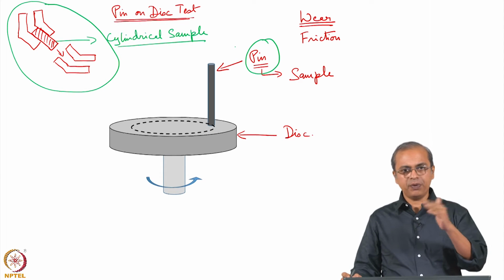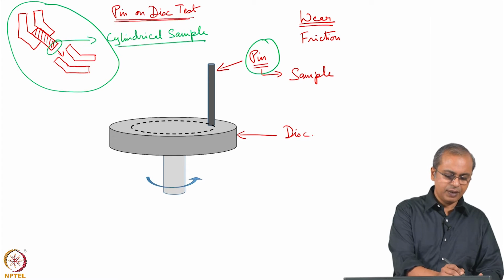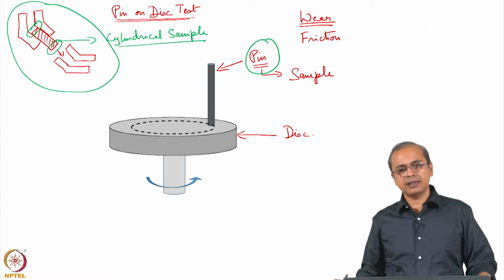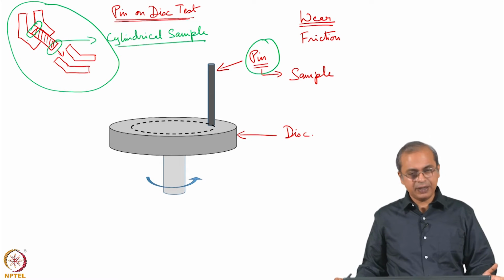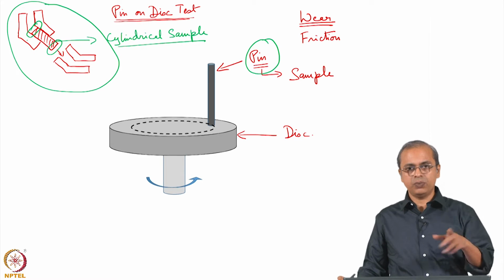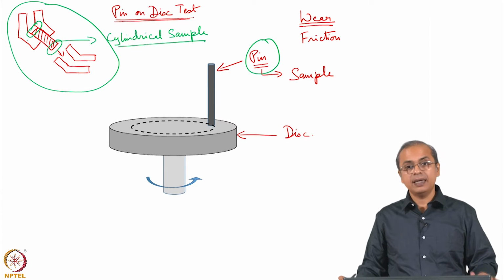Maximum, maybe you have to chop off the two ends a little bit, because usually the end will not look like a perfect cylinder's end. You may not have a perfectly flat surface there, very good chance you will not, because of all this twisting that you are doing. So, you may have to remove the two ends if it comes to that.